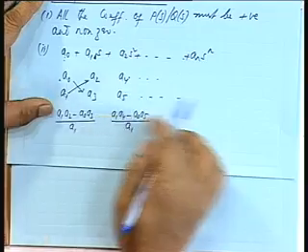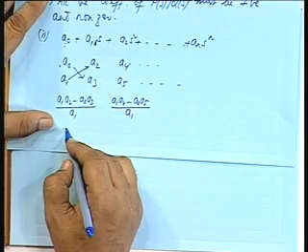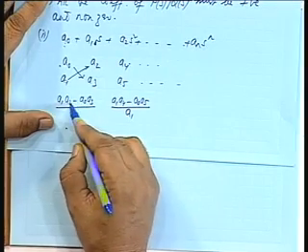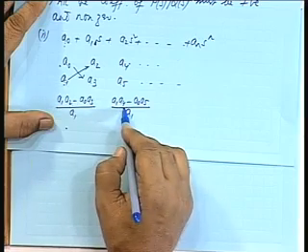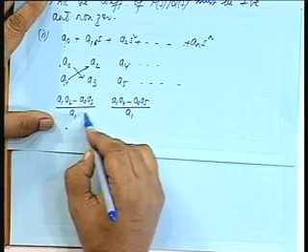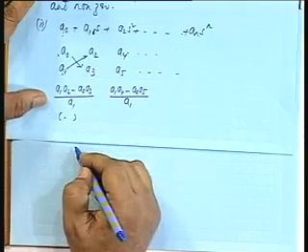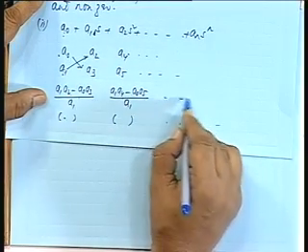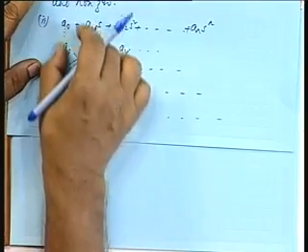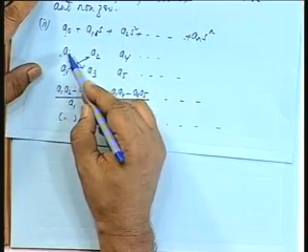So, these synthetic rows you generate, again you take this and a3 minus a1 into this quantity divided by this quantity itself, that will be the new element in this row, similarly another element and so on. After completing this, you check the signs of the first column.